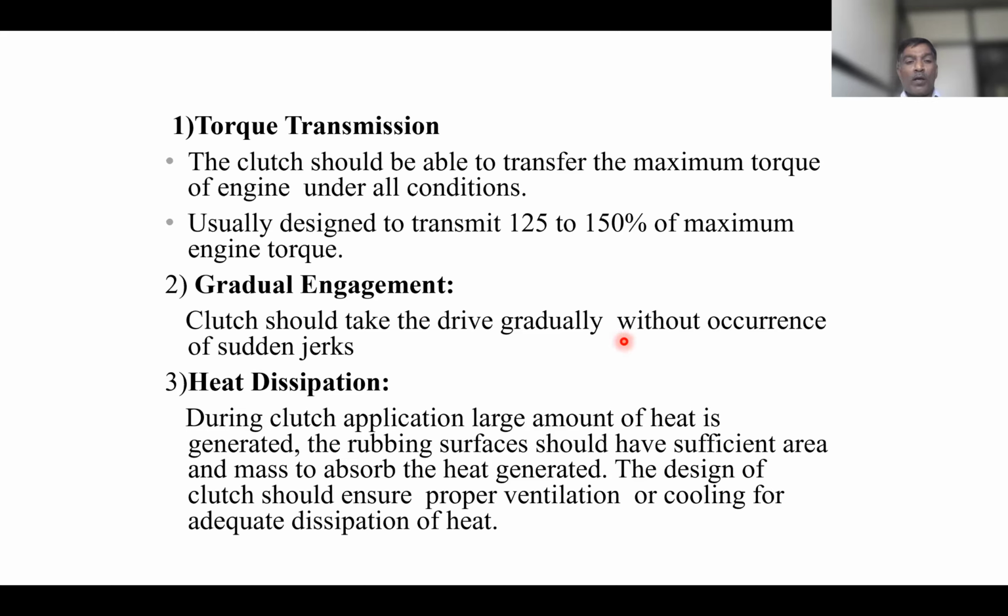Then it should have gradual engagement. The construction should be such that there is gradual engagement. The clutch should take the drive gradually without the occurrence of a sudden jerk. There should not be any sudden jerk.